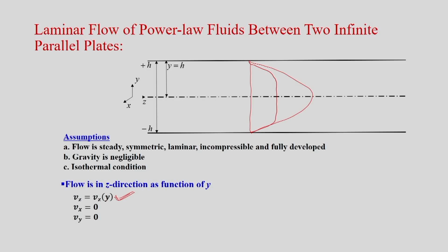Now, in order to get the velocity profiles, how do we proceed? As in this course, we start by checking the continuity equation, whether under these restrictions it is satisfied, or whether we find any boundary or limiting conditions from it. Then we simplify the momentum equation to get some information about the pressure as well as the shear stress. From there we get the velocity profile, after substituting for the shear stress in terms of the velocity gradient.